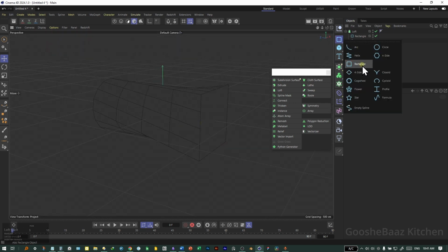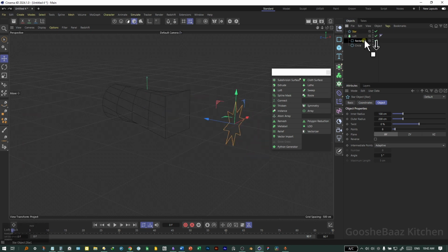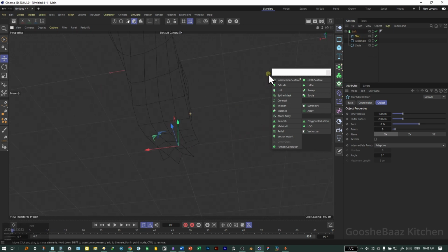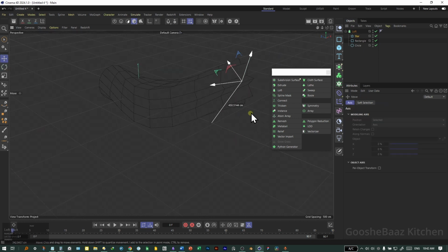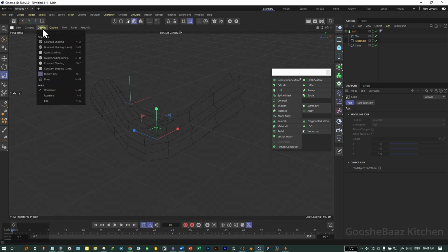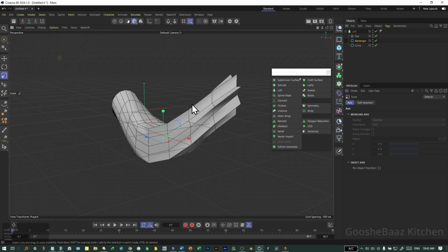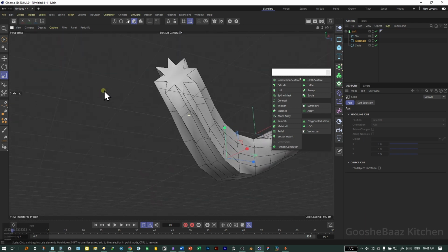For example, I can add another spline. This time let's add a star, offset it here, and add it above rectangle under loft. And as you can see, these three splines are transforming to each other in extrude fashion. I can change, rotate, and apply changes to any of these splines. Let's get back to quick shading lines and see the geometry on the surface.